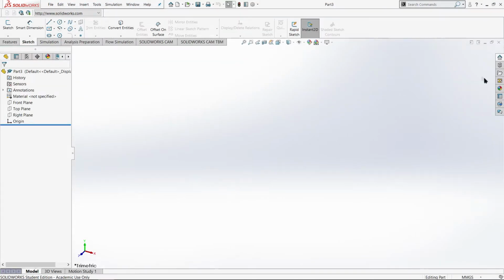The next thing we'll see is the SolidWorks 3D Design Manager. One thing to take note of is the huge window on the right hand side. This is where we will see our object, our sketch, and on the left hand side we have our feature tree, which is probably the most important thing when it comes to designing within SolidWorks. This contains all your features such as sketches, extrudes, revolves and stuff like that. So on the top left hand corner, click on Sketch, open up the Sketch tab, and this contains all our sketch tools.